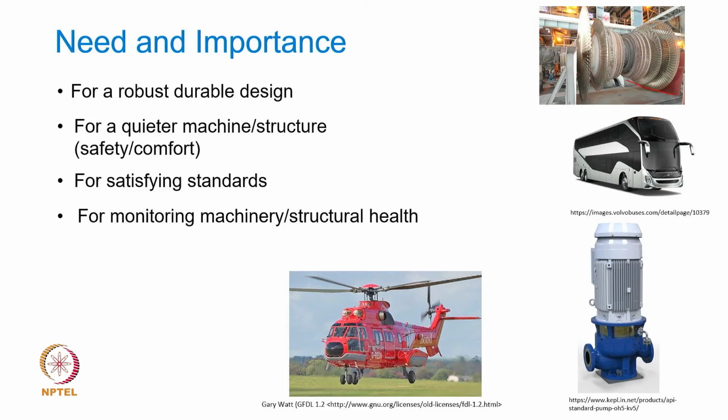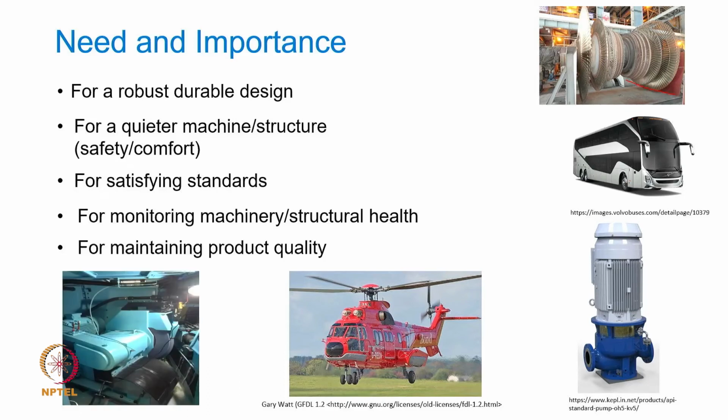So, in that case what happens is that if you are monitoring the condition of various mechanical equipment such as gearboxes or rotating shafts, and if they indicate deviation from a standard, limiting or healthy condition, we can immediately take corrective action and maintenance activities can be properly scheduled. There have been instances where early warning symptoms were ignored, resulting in loss of lives.